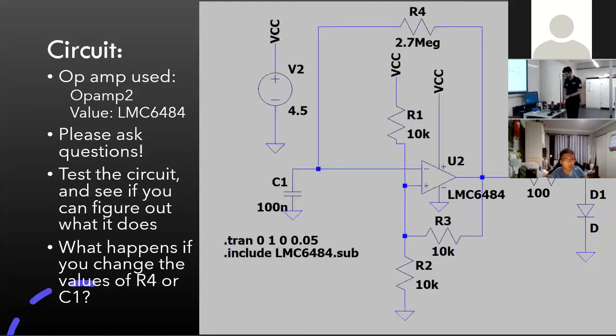Breadboards are very useful for testing. Basically, the design process for a PCB is you build it in LTspice, then build it on a breadboard, then you design it in Eagle and get it manufactured. Because once you send it off, you can't change it. On the first board that I sent off for this workshop about a week and a bit ago, I realized it was wrong after I sent it. I've changed it since then and it's right now, but I'd have to do a crazy soldering job to make it work. Actually, I just realized it won't work, so I have to send another one. I wanted to have it for next week to show you guys.